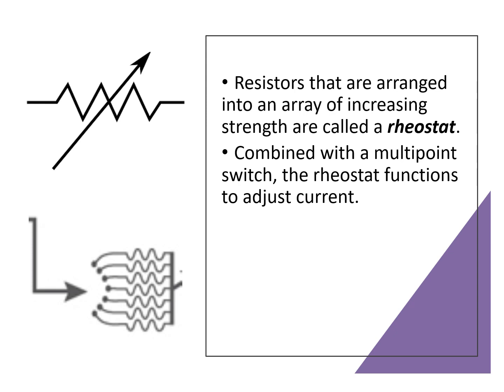Now, an electrician is going to use the top symbol here, but Mr. Bouchon uses the bottom symbol. They mean the same thing. The arrow means choose the magnitude, and then the symbol resistor is behind it. So the top symbol literally means choose the magnitude of your resistance. And so everyone knows that device is called a rheostat. Now, Bouchon's symbol diagram actually shows a multi-point switch and the array of resistors that I mentioned. And so Bouchon's diagram of a rheostat is closer to what it actually looks like if you were to view a rheostat.